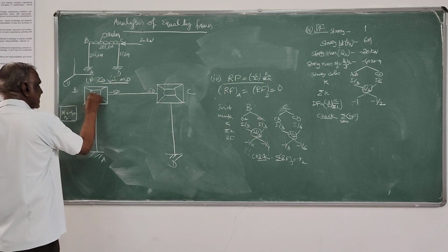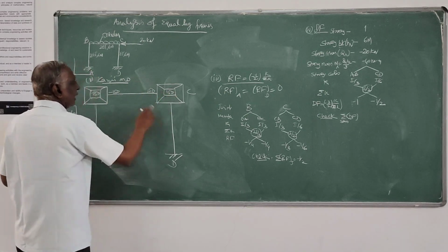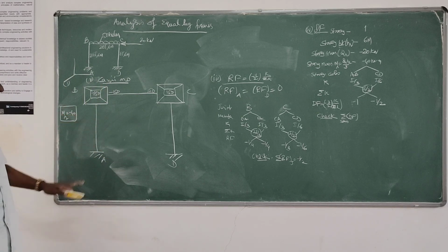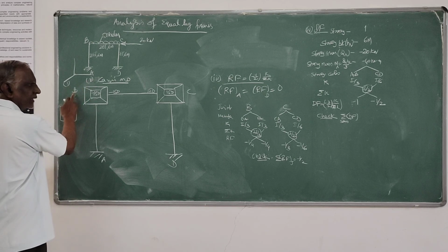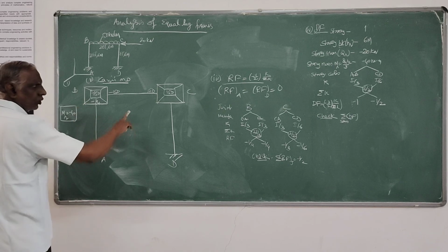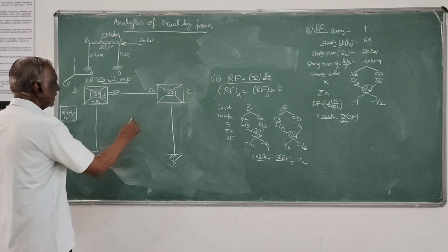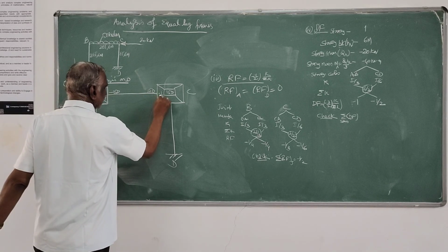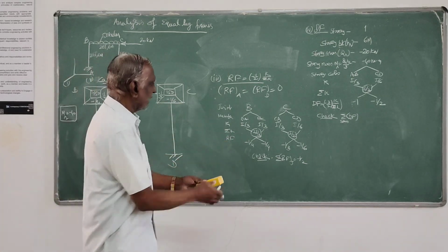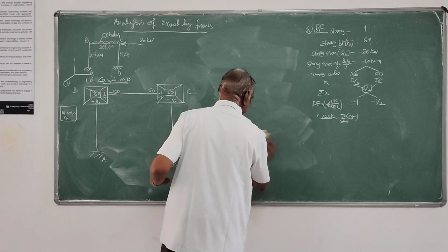Here I will find out the sum of the fixed end moments at each joint, at joints B and C. Then the rotation factors: at joint B, for BA it is minus 1 by 4 and BC minus 1 by 4. At joint C, CB is minus 1 by 3, CD is minus 1 by 6. I have transferred all the rotation factors into that diagram.